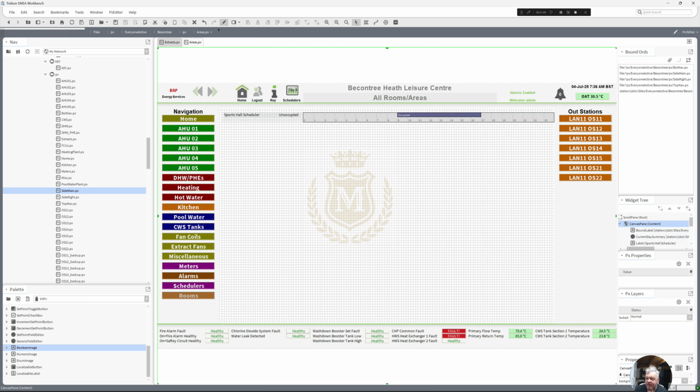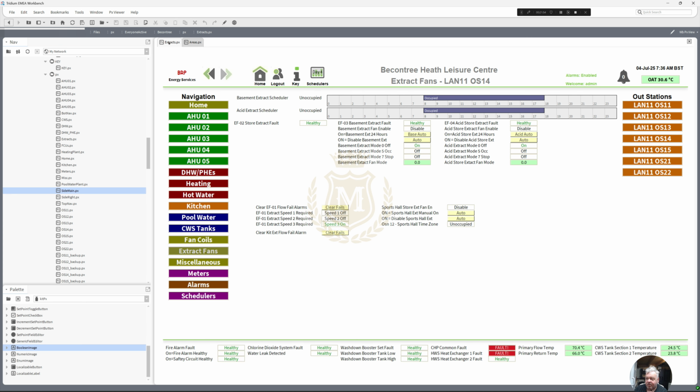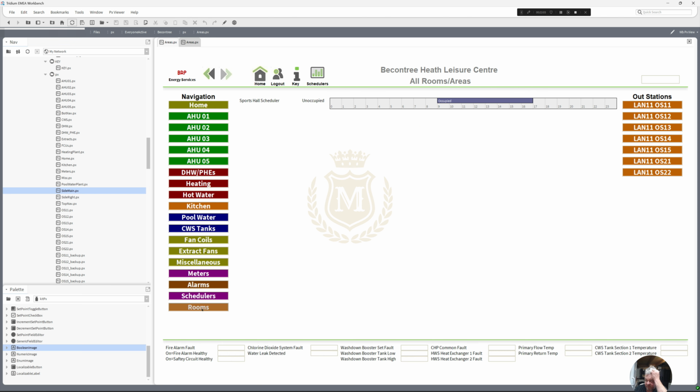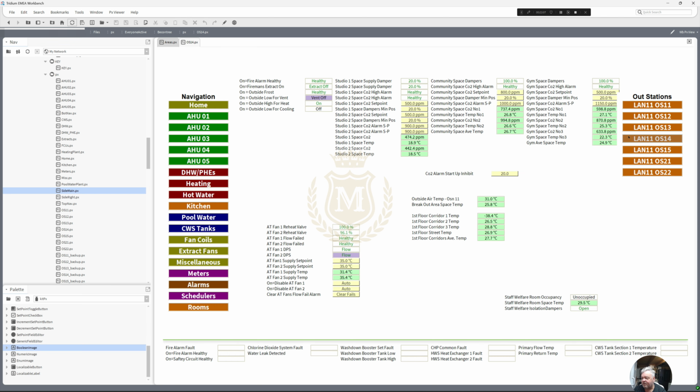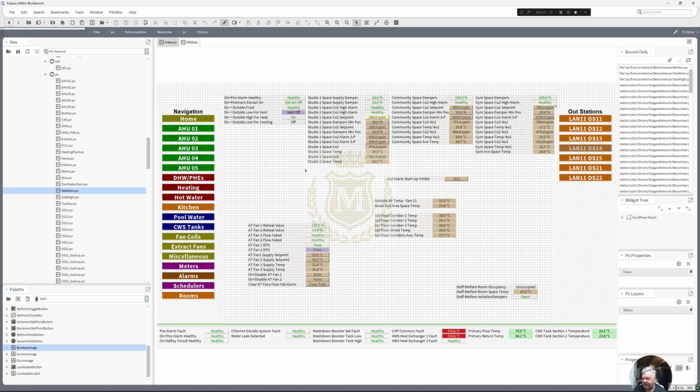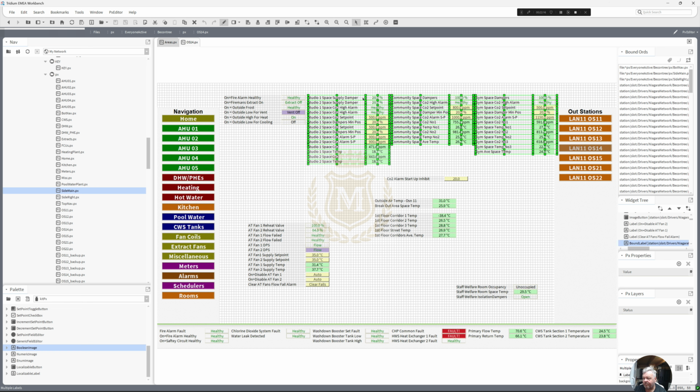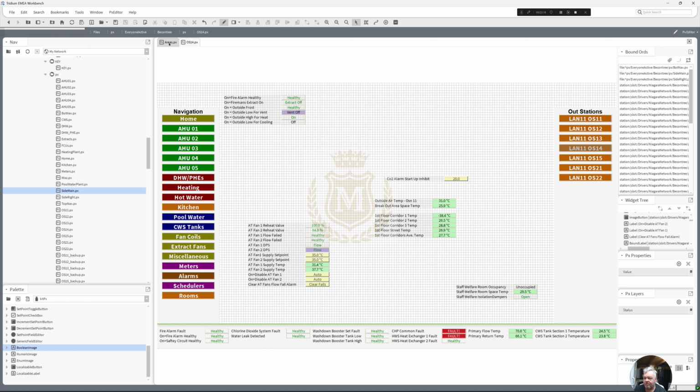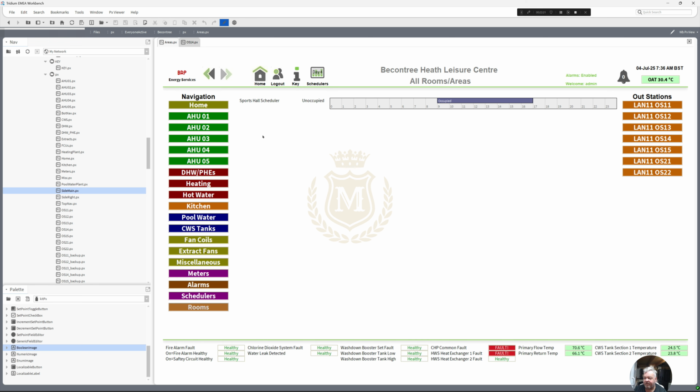Now we're in there. Let me come out to edit mode, left hand side, go back, we need to refresh that, go back to rooms, click on areas, and it was land 14, and we can take them, cut them, and paste them into here.